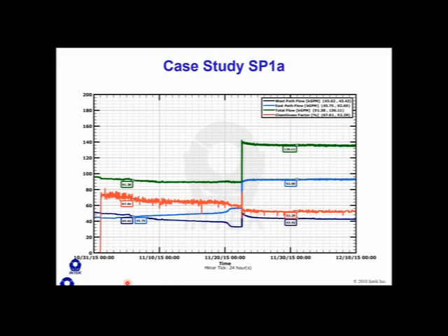So what's the issue? What's happening in here is, let's take a look at the west path, just the red line here. The cooling water comes up to a value and it starts decreasing. Cooling water is decreasing. And at the same time, we're seeing the east path increasing by almost the same value. It's as if the flow rate is shifting from west to east.